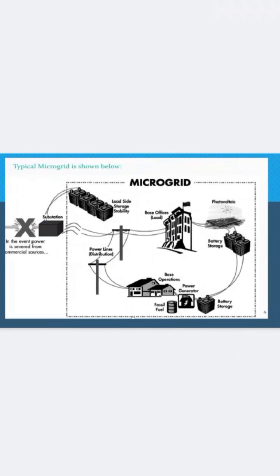In this typical microgrid diagram, the main substation provides the power to a particular area by point of common coupling. Also, in this diagram, a microgrid is connected to the grid at a point of common coupling that maintains voltage at the same level as the main grid unless there is some sort of problem on the grid or other reasons to disconnect. A switch can separate the microgrid from the main grid automatically or manually, and it then functions as an island.